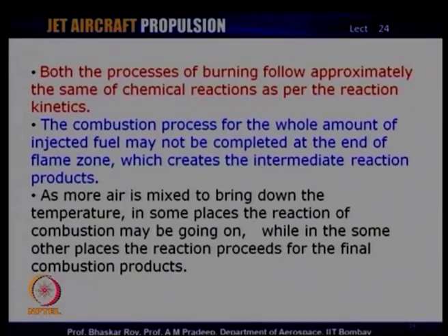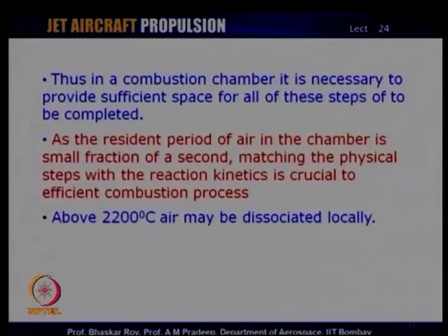So, in the secondary or tertiary zone or in the dilution zone, it is entirely possible that a very small amount of combustion is still going on, but most of the combustion, 98% of the combustion, may have already been completed. So, this is how the combustion is indeed done inside the combustion chamber.